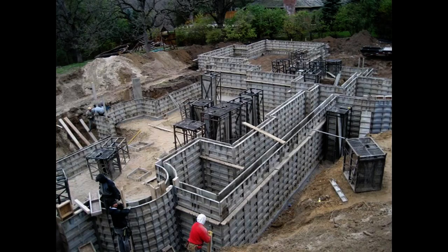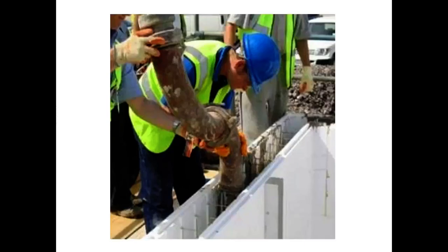Modern shuttering takes all sorts of shapes and forms. The sort of shuttering we're looking at here is steel, which can be reused. You pour the concrete into it, you can take it away and reuse it. With timber, in the old days when we used much more timber shuttering, and we still do in various parts of the world, the timber, once it's been used, tends to be discarded, so it's not very efficient. Here we are pouring into. In fact, in this case, the shuttering is a kind of insulating material, which is interesting.